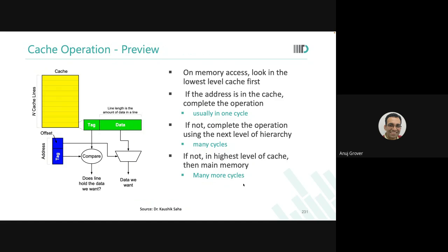Do you understand the term coherence? What does coherence mean? And the content is exactly the same. See, when I say that this address should be available in all the memories, the address may be available, but I'm saying they may not be coherent. It may be that in the local copy that you have in L1 cache, the content could be different than the content available in L2 cache. Why and how will this be the case?